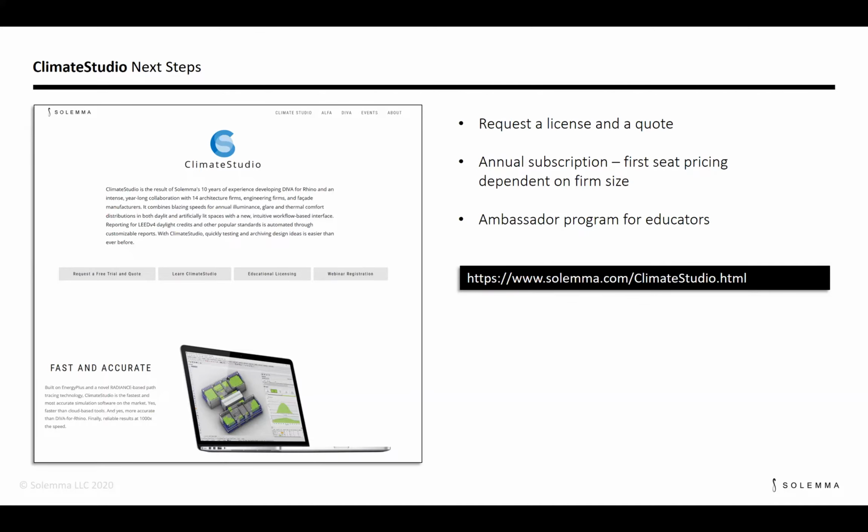Yes, you can use BSDF functions if you want to do an annual glare and point-in-time illuminance analysis. For the link between the energy modeling and the lighting models, that's a good question. What's the link between the artificial lighting and the energy analysis and the daylighting analysis? The link is right now not automated yet, but as you just saw, Jon was doing a daylighting analysis and an electric lighting analysis, and that helped us set a proper lighting power density. On Thursday, we will be picking up from what we left off here and use the lighting power density from the daylighting analysis to explore what impact that has on the thermal side for heating and cooling and so forth as well.